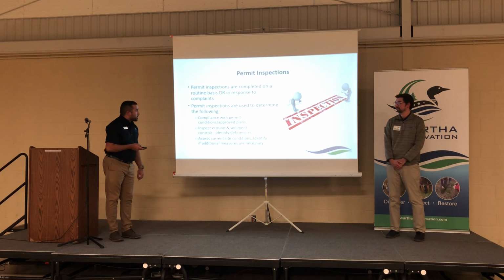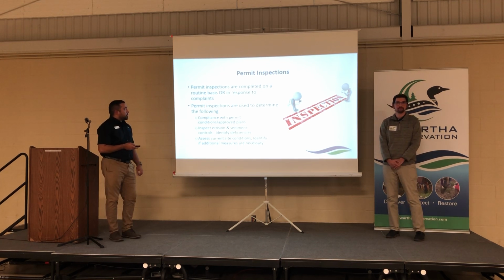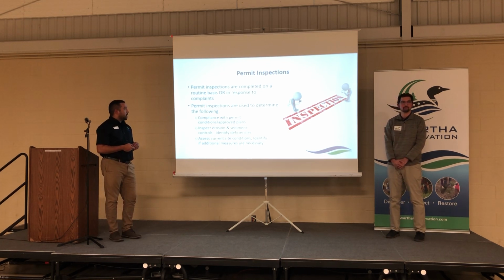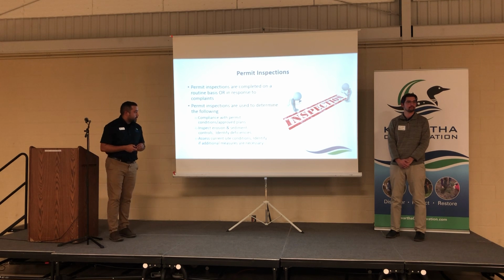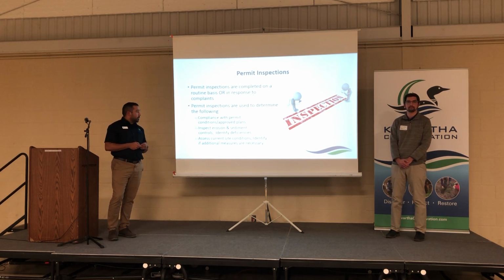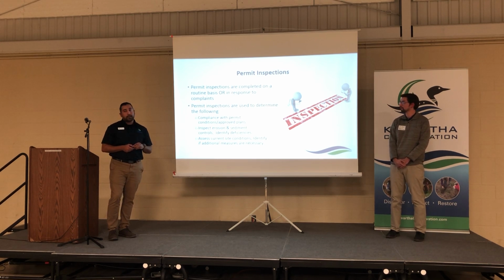So for permit inspections, these are completed on a routine basis or in response to complaints. They're usually used to determine compliance with the permit conditions and the approved plans, to inspect erosion and sediment controls, to identify any deficiencies within those controls, and also to assess the current site conditions to identify if there are additional measures needed in order to contain sediment and silt on the site.